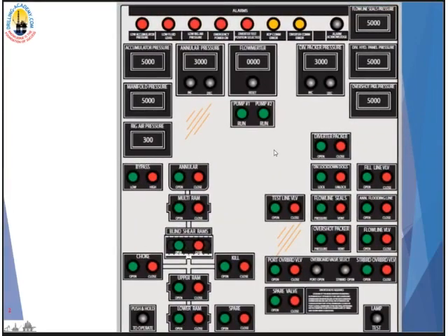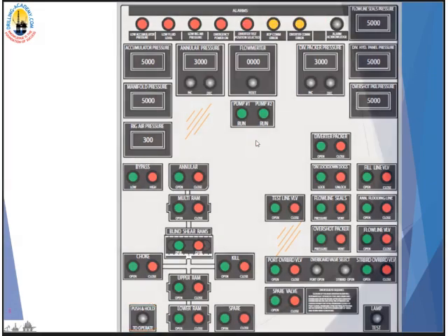This is the close-up view of a modern model of a remote control panel. This is a fully touch screen. There is no physical push release button, but there are all touch buttons in here. And there is one master touch button here. You touch, push and hold to activate the functions on the BOP and the diverters. On this touch panel, there are displays of alarms and faults. You can do the fault finding on this panel.